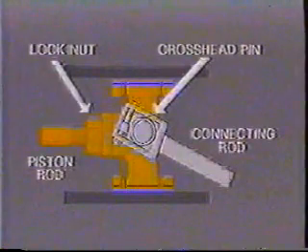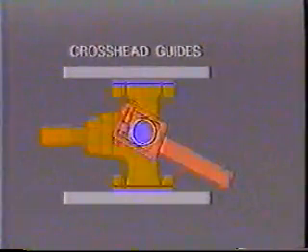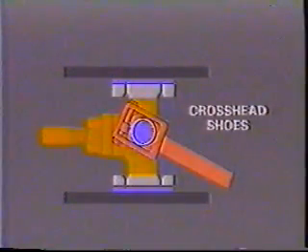The crosshead travels horizontally and must have limited vertical variation. This confinement is maintained by the flat or circularly bored crosshead guides. Inside the guides, the crosshead shoes maintain the vertical position of the crosshead. While the shoes are replaceable and adjustable, shims on both of the shoes provide additional adjustment.